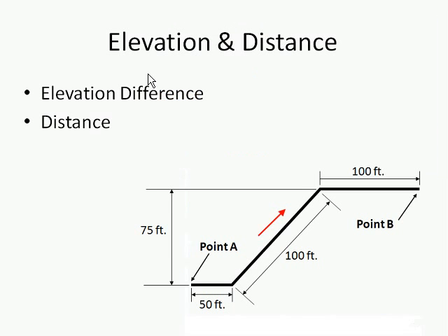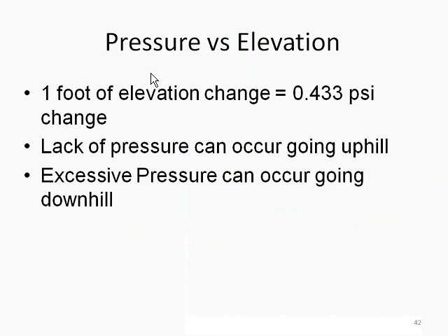Elevation difference, pretty simple. We need to know how much difference there is in elevation between the source and the trough, how much distance there is from point A to point B. It's important to know elevation difference because as you change elevation, that change in elevation impacts the amount of pressure that you have to overcome.